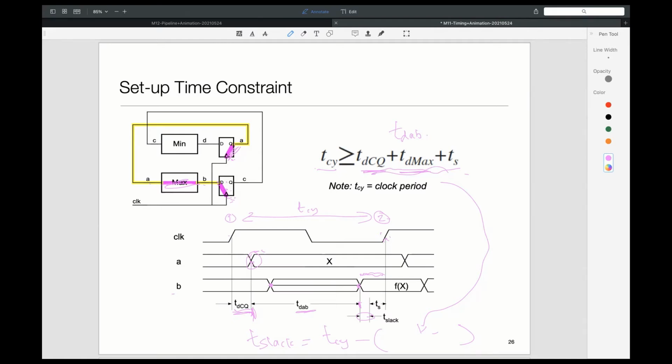And in fact, let's say it turns out that the delay of your circuit depends upon something. Let's say it depends upon temperature. Then, as the temperature goes up, the combinational delays tend to go higher. So generally, as the temperature goes up, gates get slower.